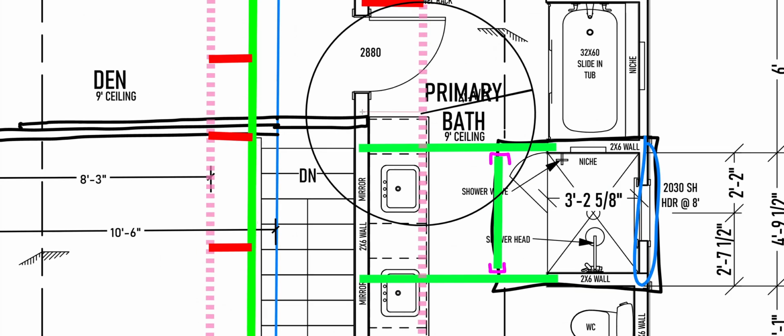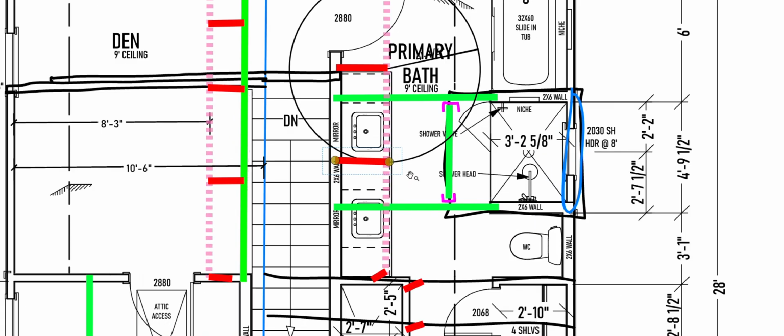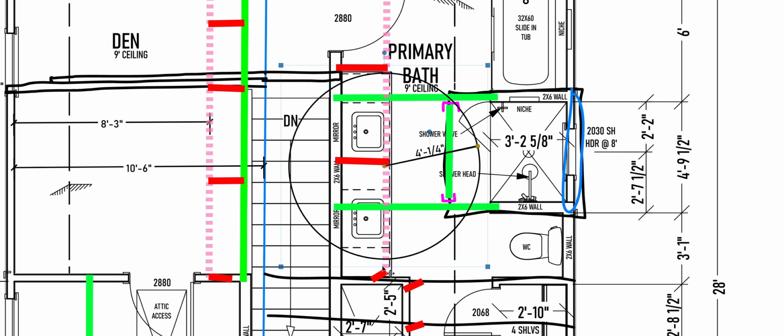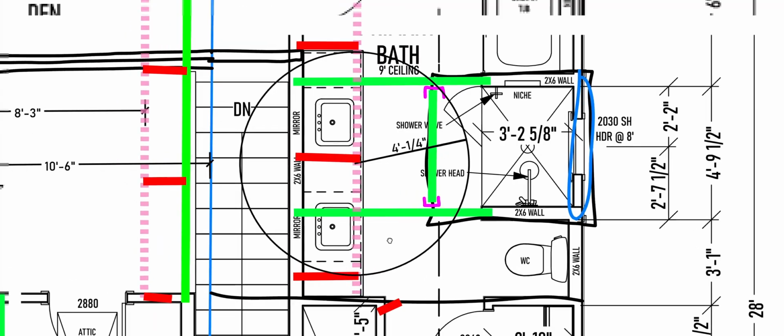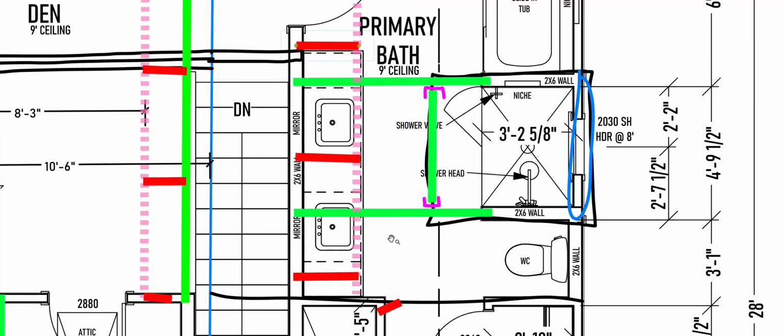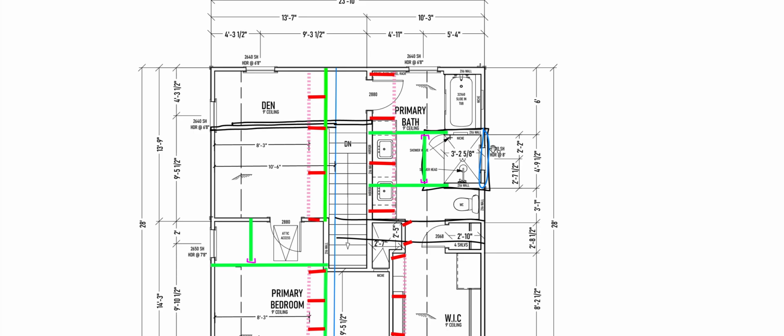So I need a brace right here. I need a brace right here. And that's probably about 4 feet. It's kind of stretching 4 feet. So what I'm going to do is I'm just going to take this brace, and it was at the end. This is all going to depend on my exact rafter layout, so not a big deal. Okay, so that's approximately where I'm going to put those braces for the purlins.